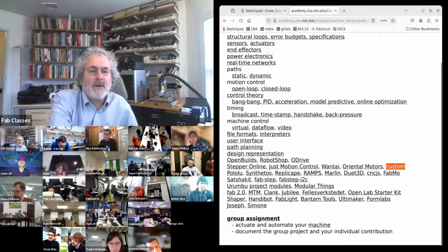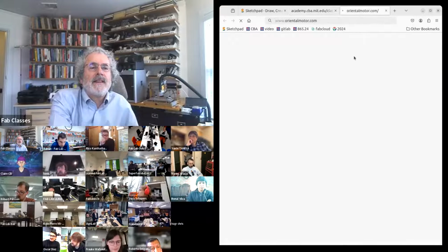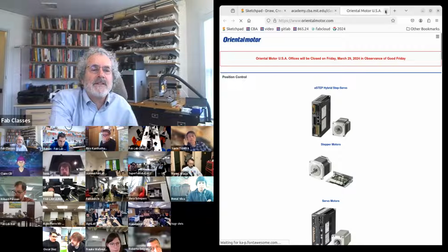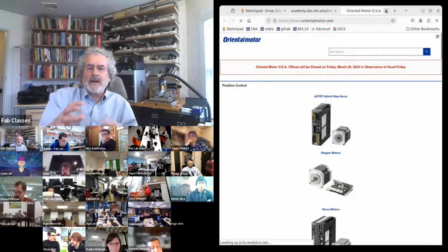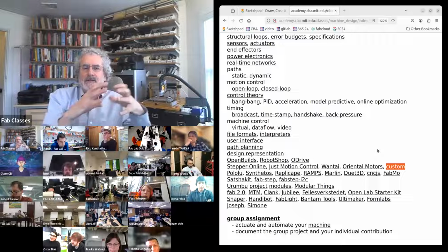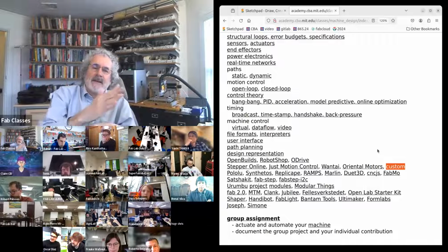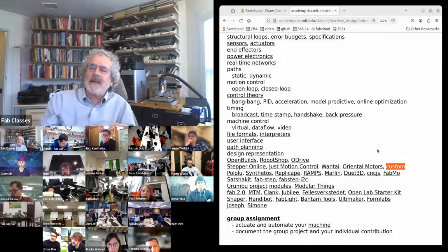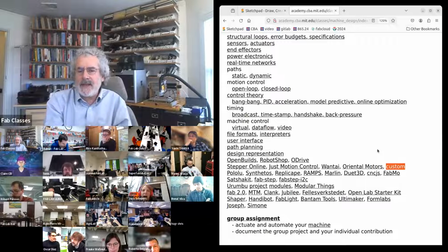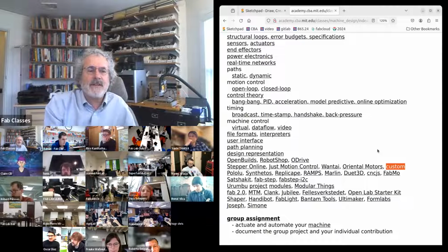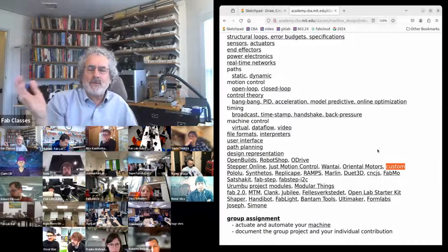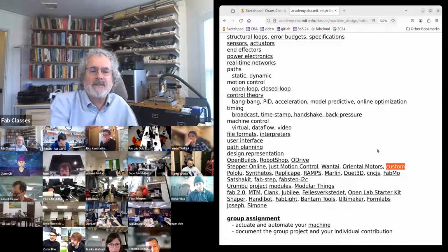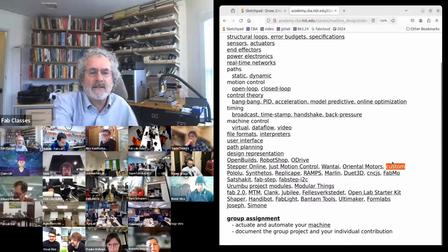And one of the things to know is, thanks to our friends in Shenzhen, they can very easily customize your motor. Not for a single one, but if you want a motor of a certain package size with a certain torque, given a step size, and if you want, for example, an integrated lead screw with an anti-backlash nut or whatever fittings, once you get up to 10 motors, it's surprisingly accessible now to order custom motors from those vendors.